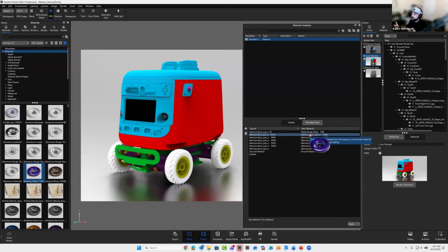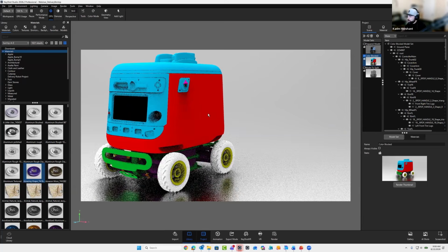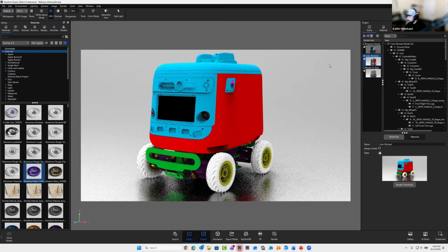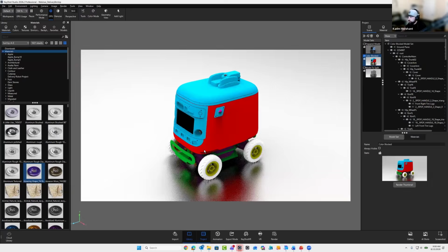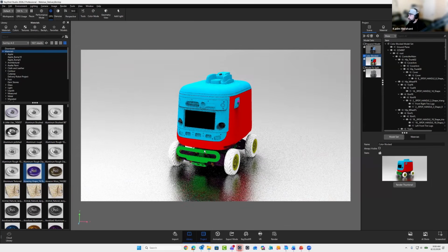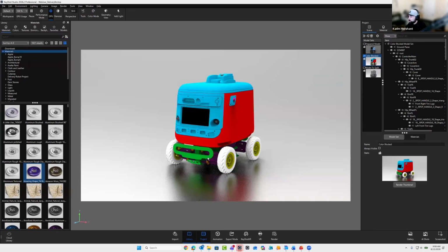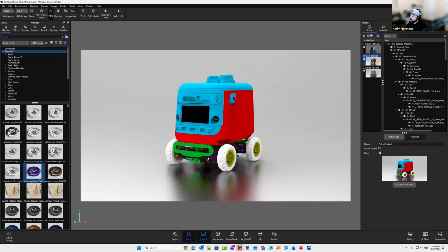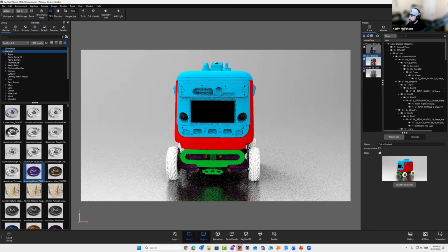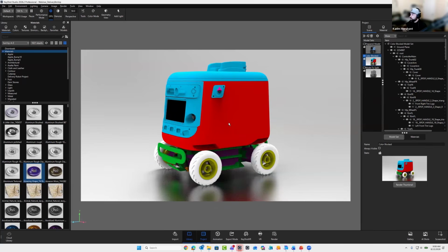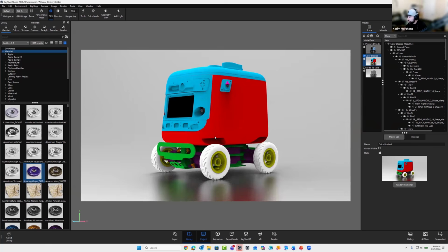That way, when you're importing your models using a material template, you're going to end up with a level of base materials already applied to your model, and then you don't have to go through the process of actually applying them. At that point, it's just customizing your materials, dealing with your lighting, dealing with your cameras, and then your final output. So it's even faster than working with color blocking, a little bit more of an advanced tool, but it's super useful, especially if you're using similar materials over and over. It just simplifies the entire process. But that's two ways we can color block and import CAD data so that it's already prepped and we don't need to worry too much about prepping our models in KeyShot.